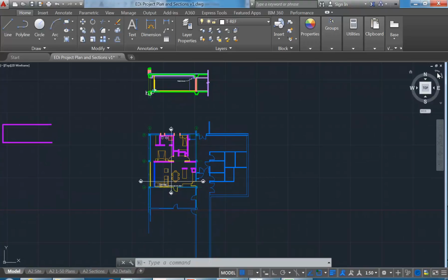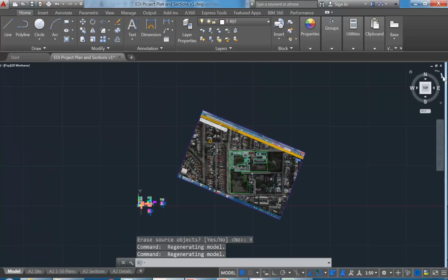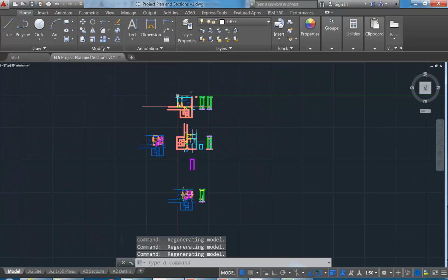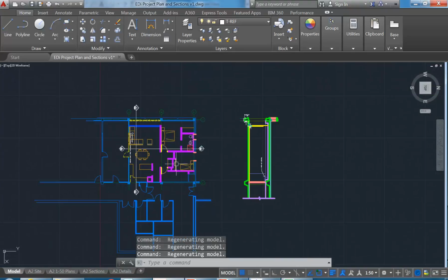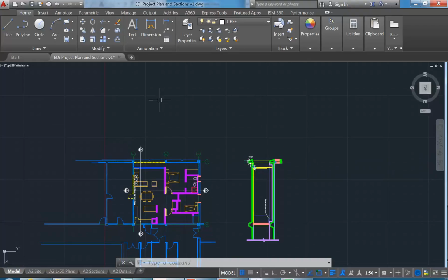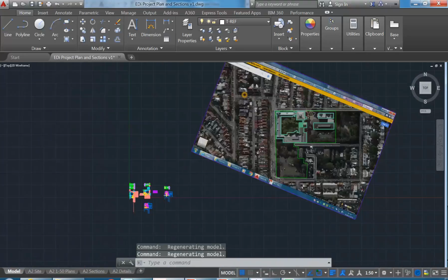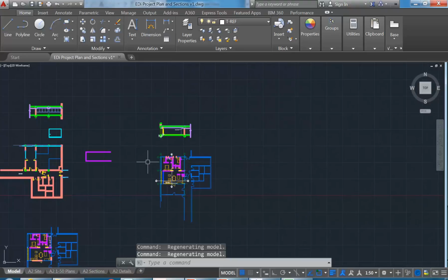So you can do the method I was talking about initially, which is to rotate the whole view. In some ways it is good, because you're projecting from the same floor plan. So if you know you're going to keep doing more work on your plan, that's good, because you can then easily update your sections as your plan changes. But if your plan's fairly complete, then it's actually better the other way, and that's the way I'm going to do it.